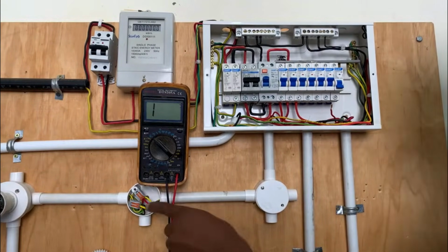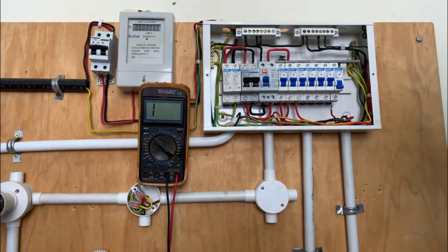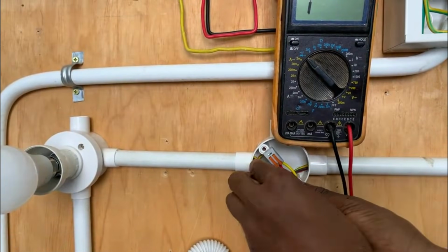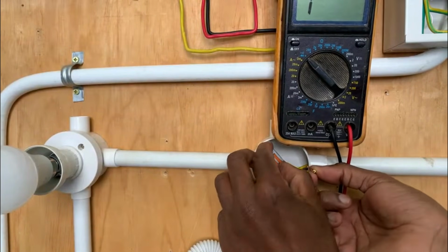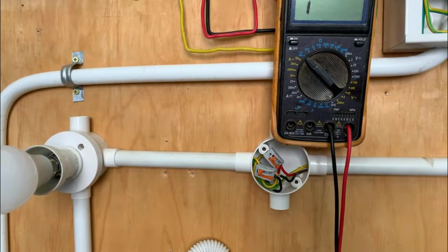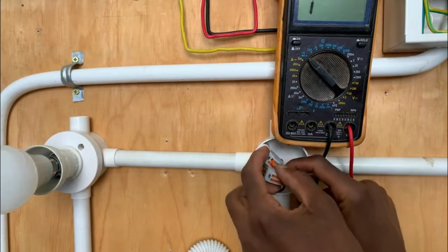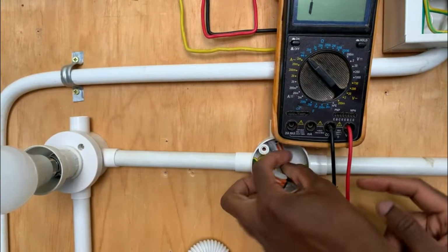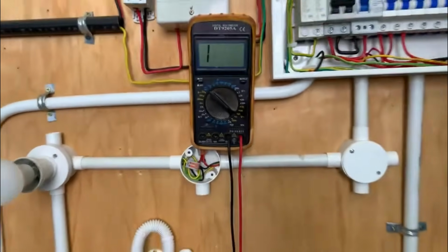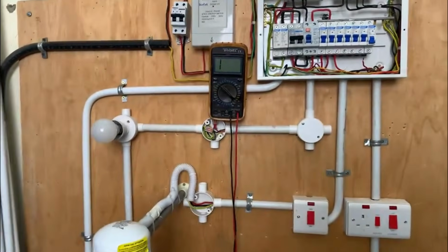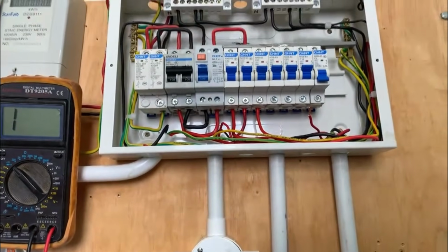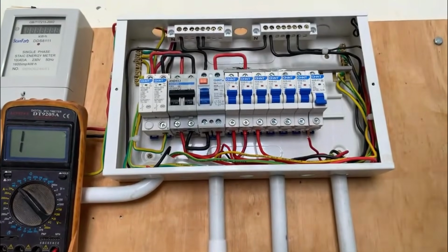So the problem is we have identified, from what our makeshift problem is at this point here. So let us remove this short circuit by simply disconnecting the jumper wire that we had connected, short circuiting the line and the neutral. So we get it back like that. On this one, get it back. So there is no short circuiting between the neutral and the phase, or between the line and the neutral. And then we come back here again and we record between the output, assuming that we are still troubleshooting the problem and solving. All right.